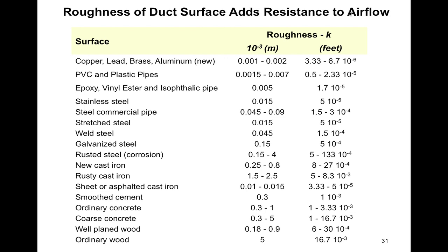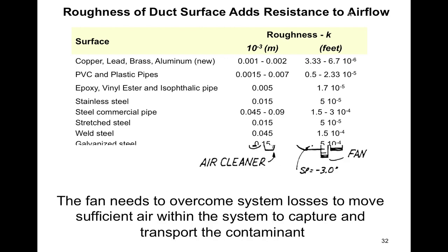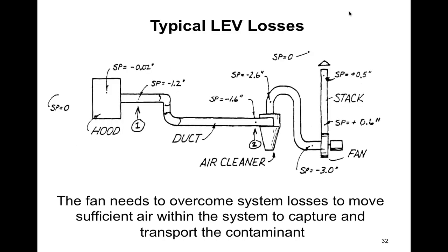What did we say about this? Laminar flow is under 2,000, right? What they define from Reynolds numbers, laminar flow, between 2,000 and 4,000 is kind of in between, right? And above 4,000 is basically you treat it as turbulent flow. So basically, we're never going to run into a system, most likely, that's laminar flow. We're always going to be dealing with turbulent flow.